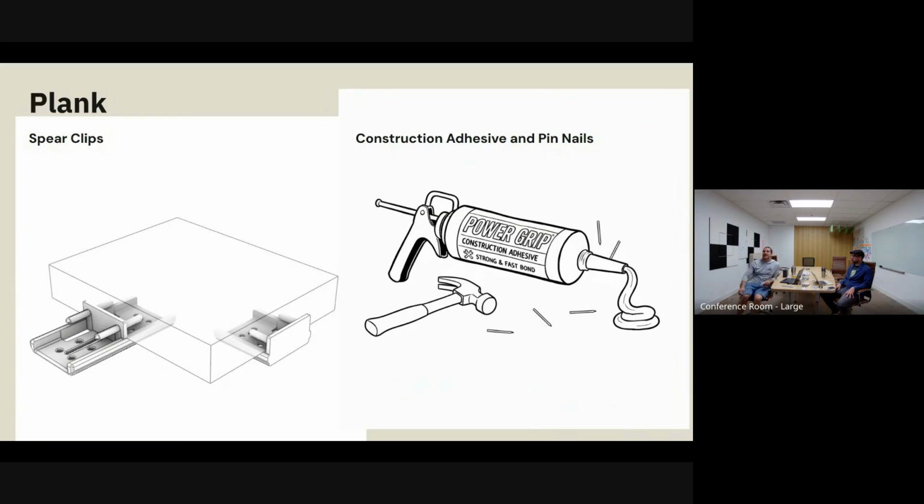You've got to have a flat surface, so it's got to be either a plywood deck, a plywood wall that is very flat and level, or a level 4 or 5 finished drywall surface to do this. Because otherwise, if you have waves and variations in your wall or ceiling, the panels are going to follow that, and you're going to see it, right? If you use the construction adhesive and pin nails.